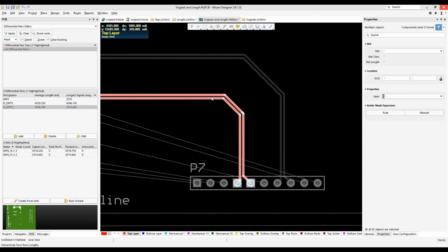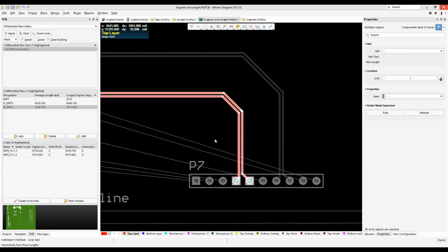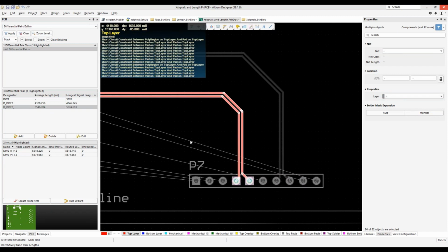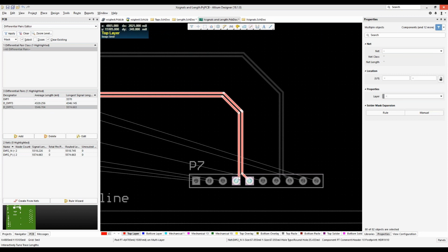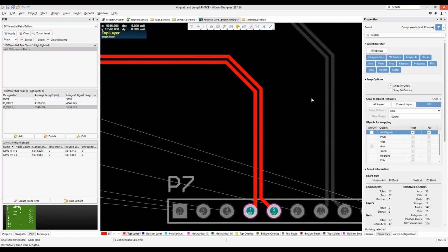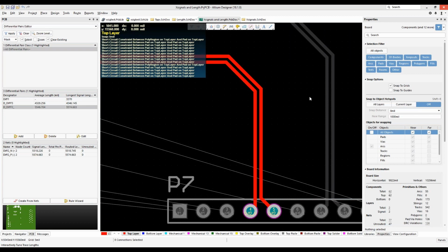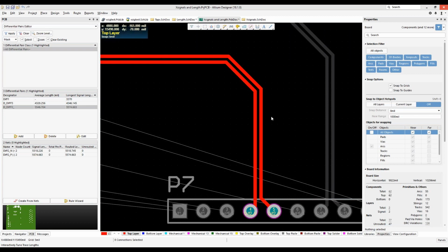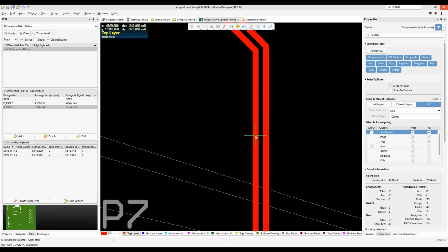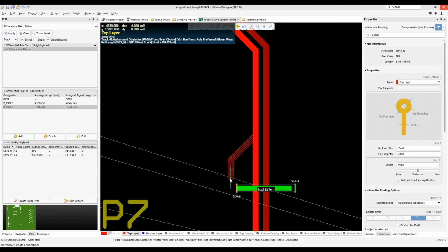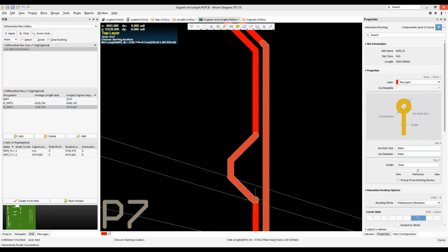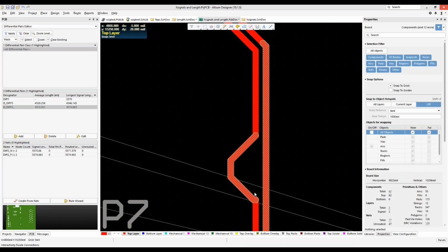It's just that once we got over here to this bend, that's when the trace lengths got much different. And again, one of the rules with differential pairs is you want this to arrive at the same time for the receiver. So how do we fix that? Well, there's a little tool that a lot of you have probably been using, and we're going to take advantage of that. You may know that if you start a route, and you go on in here and start doing something like this, once I'm done with this over here, it's going to remove the original piece.